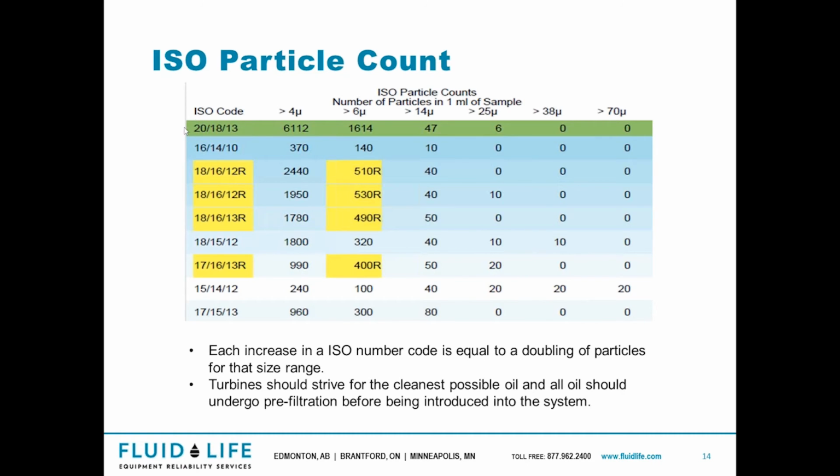And so you have, this is the new oil. It's actually much dirtier than what's expected in the turbine. And most new oils are dirtier than what should be run. And so any pre-filtration of new oil should also be mandatory for any turbine application.